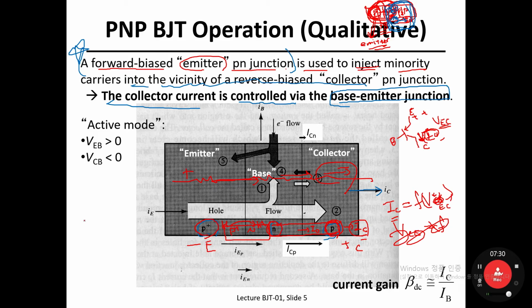So going back to the original definition of a transistor, a transistor has three terminals. One, two, three. And the current flow between two terminals, say terminal 1 and terminal 2, has nothing to do with the voltage difference between those two terminals. But this current flow I12 is fully dependent on the third terminal, say V3.